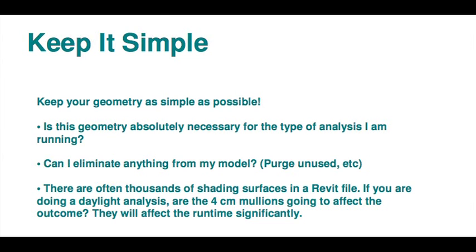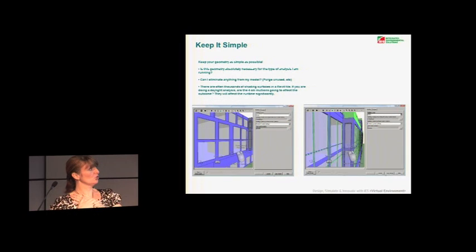Use the appropriate family type for custom components. Choose the lowest level of complexity. And I think Michelle will cover that in the demo as well. So there are different levels of complexity that you can export. Use the lowest one that you think you can, for the stage in the design process that you're at and the purpose of the analysis that you're actually going to be carrying out.